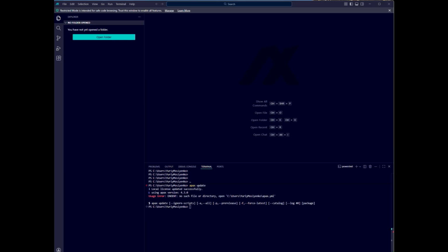Okay, now let's create the project in SIMATIC AX. So I open the software itself, which is generally the VS Code fork. We have to remember that actually SIMATIC AX, at least for now, doesn't like the folders with names contain spaces. Probably later it will be fixed, but this is the reality right now. So I created not in a folder where I collect all the information and progress notes, but in just a root folder with my local projects.